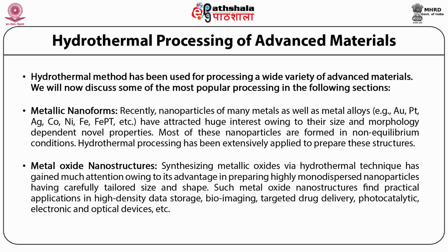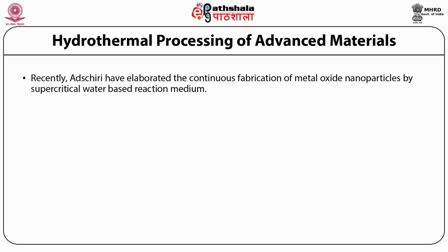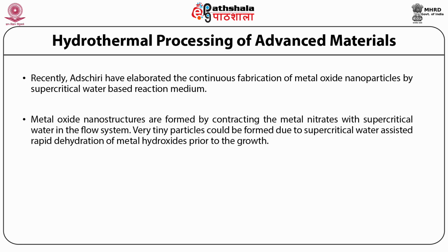Recently, Adschiri et al. have elaborated the continuous fabrication of metal oxide nanoparticles by a supercritical water-based reaction medium. Metal oxide nanostructures are formed by contacting the metal nitrates with supercritical water in the flow system. Very tiny particles could be formed due to supercritical water assisted rapid dehydration of metal hydroxides prior to the growth.